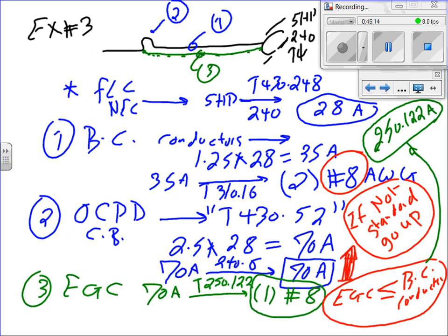So I got a question. Because of the inrush current, the 70 amps, you don't have to reconfigure your branch circuit conductors to accommodate the 70 amp breaker. Good point. Now, look at this. I have a number 8 conductor. That's where I get all these messages. I told you guys, Chad, you can't believe what I saw. What did you see? I saw number 14 conductors and there's a 40 amp breaker tied to it. It's okay. It's feeding a motor. So a lot of people, if you look at number 8, normally number 8 can be protected with what? 40 amps. Right? 40 amps for number 8.